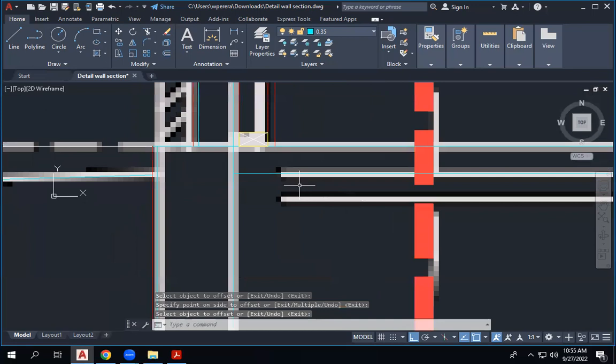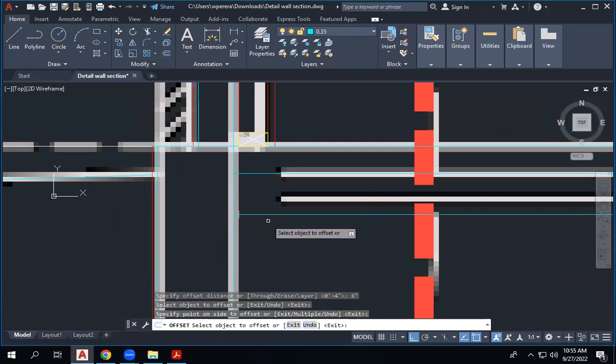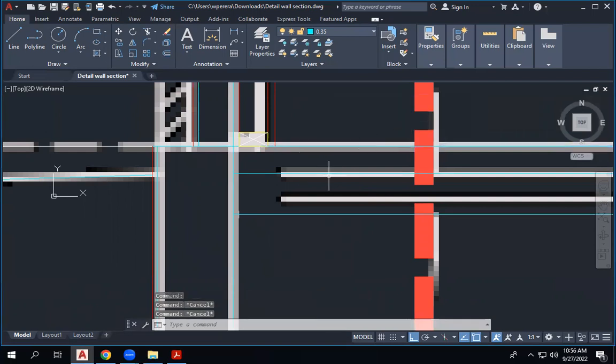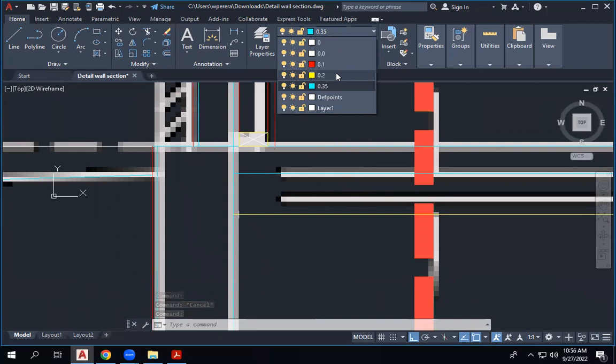Right, 4 inches here. And we will take another. It doesn't matter, I'm going to put 6 inches, because on most sites 6 inches is the adequate, minimum size for the filling. 2-3 inches is not enough. Which one was 6 inches? I'm going to put it here, the filling. So these two I am keeping as 0.35, that's concrete, but for the filling I am going to change the line thickness to 0.2.